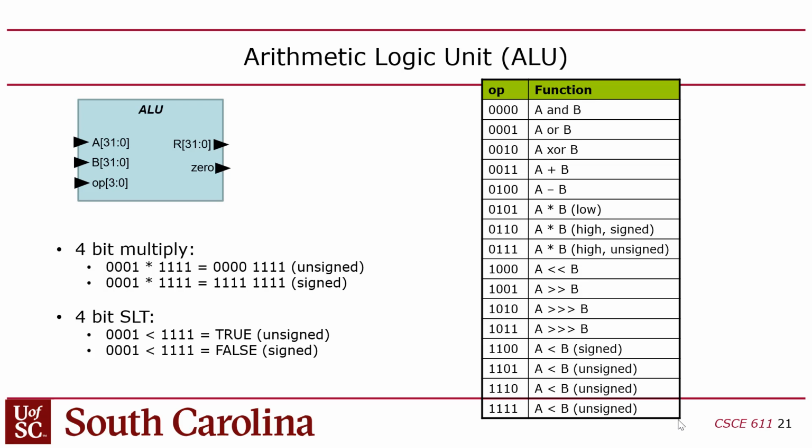Meaning your program would crash, essentially. You would run code and it would crash if you got an exception. Most CPUs don't have that. They don't check for overflow or underflow for integer add and subtract. Meaning if it happens, your program produces the wrong result, but it doesn't crash. MIPS had this exception that would literally go into the operating system and then cause the operating system to kill the process. But they got rid of that in RISC-V, thankfully.